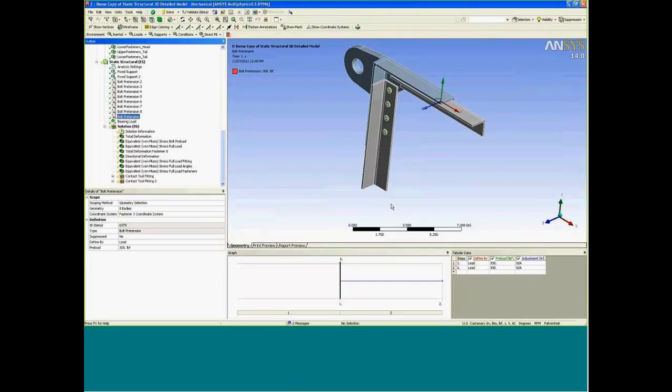One thing in this bolt pretension we just set up, you'll see it's automatically set to load in each load step. What we want to do is switch this over for the second load step to lock this in place. So you click on the load icon, click on lock, and that will automatically lock this in place. That's important because the iteration to resolve the preload is already taken care of, so you want to lock the 2 halves of the bolt in place, and we can monitor the bolt pretension later on in the results post-processing. Okay, that's some of the specifics for bolt pretension and bolted joint setup.